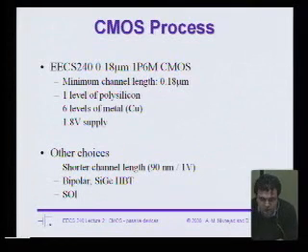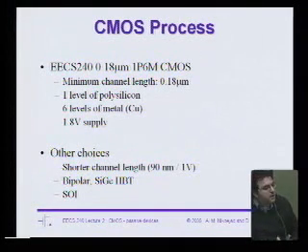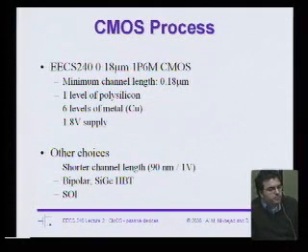Another subtle thing to bring up here is portability. CMOS processes tend to be pretty portable these days. So if I design in one flavor of 0.18, it doesn't take me that much work to port my design to another flavor. In fact, a lot of times you can just tape the chip out again and get very comparable performance. So that's really nice. That's a very, very good thing, having something that's portable.